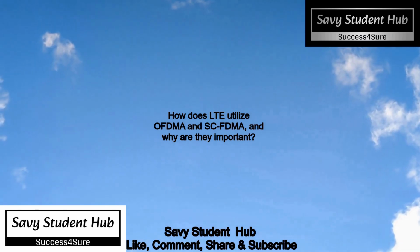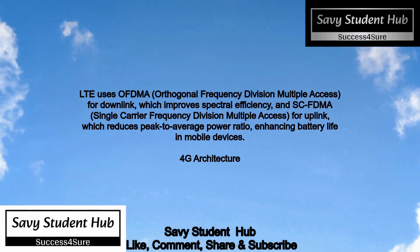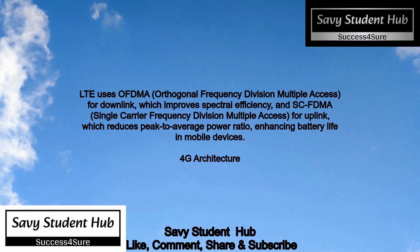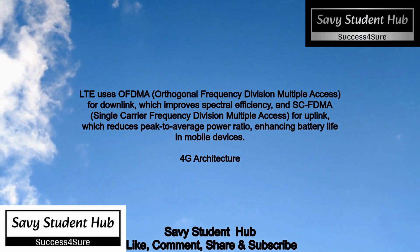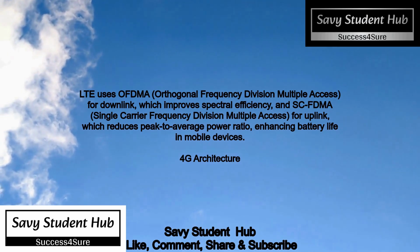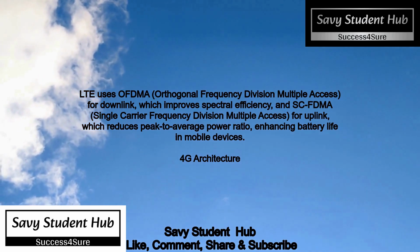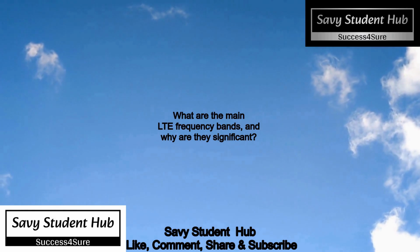LTE uses OFDMA, orthogonal frequency division multiple access, for downlink, which improves spectral efficiency, and SC-FDMA, single carrier frequency division multiple access, for uplink, which reduces peak to average power ratio, enhancing battery life in mobile devices.